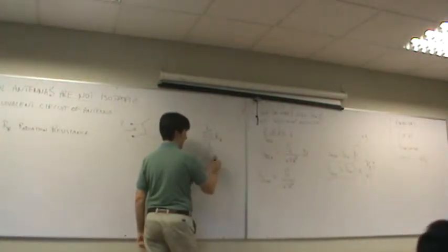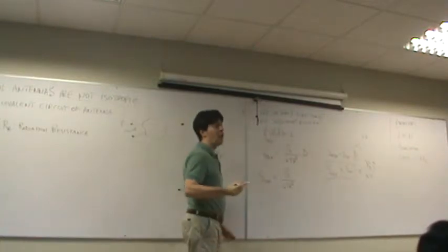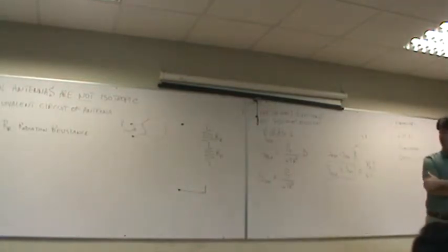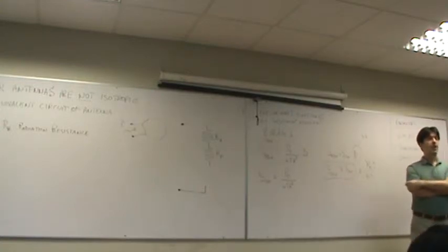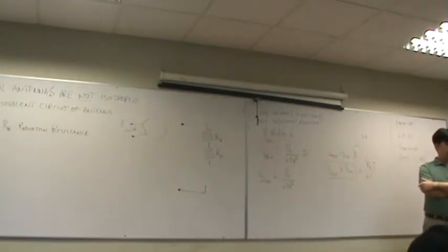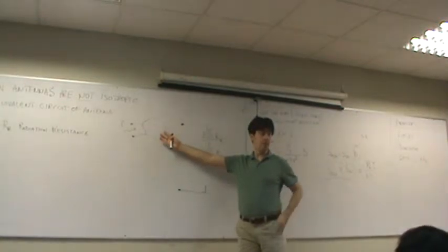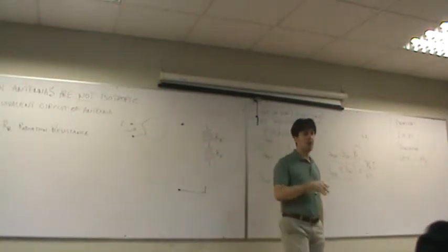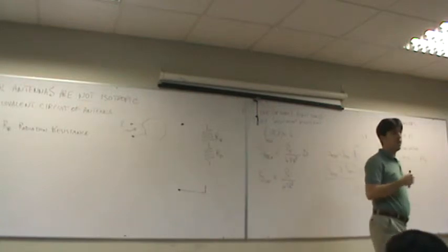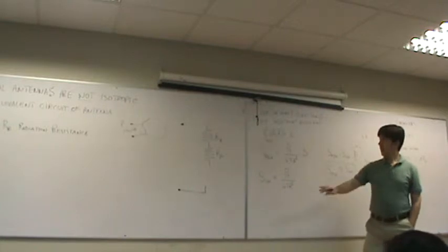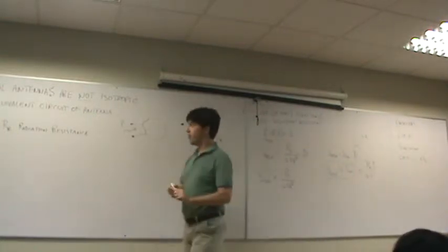Again, another resistance, the only component that can absorb and dissipate power. This time, this resistance has a completely physical meaning. This is an actual resistance. That is, the antenna actually warms up. It can actually melt down if you put too much power. You can actually burn the antenna and melt it. This is called loss resistance.